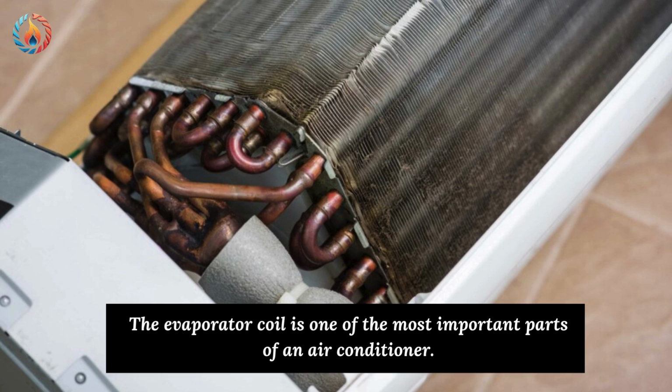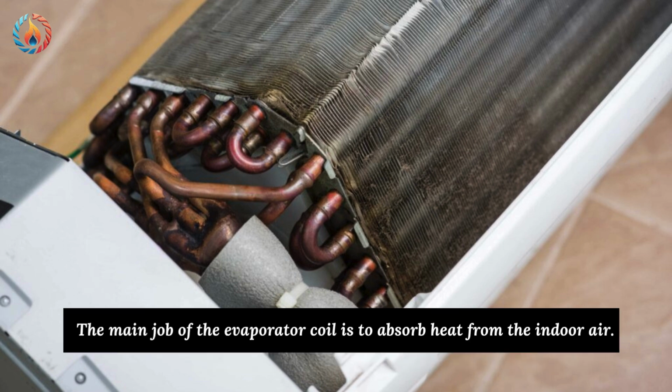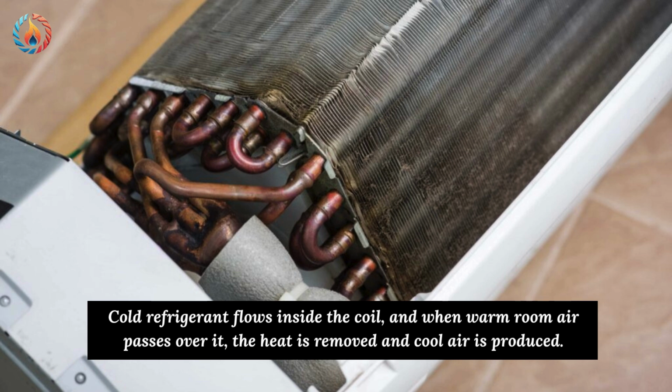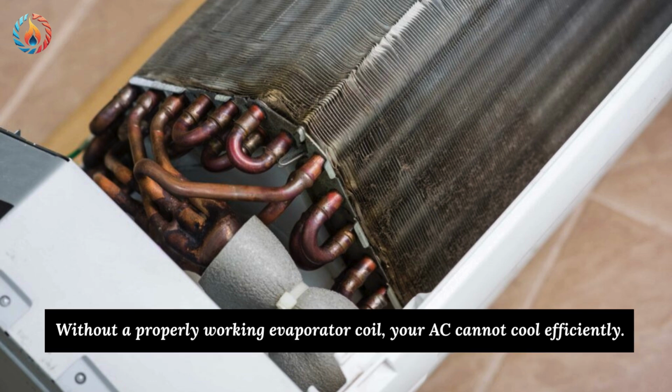The evaporator coil is one of the most important parts of an air conditioner. It is usually located inside the indoor unit near the blower fan. The main job of the evaporator coil is to absorb heat from the indoor air. Cold refrigerant flows inside the coil, and when warm room air passes over it, the heat is removed and cool air is produced. At the same time, the coil also removes moisture from the air, helping reduce indoor humidity. Without a properly working evaporator coil, your AC cannot cool efficiently.